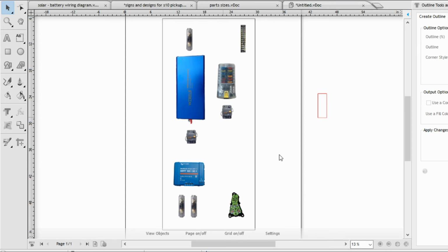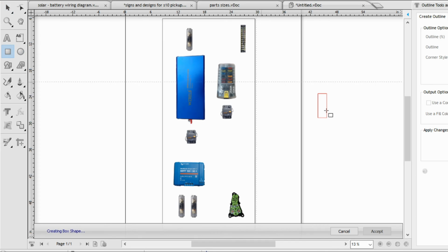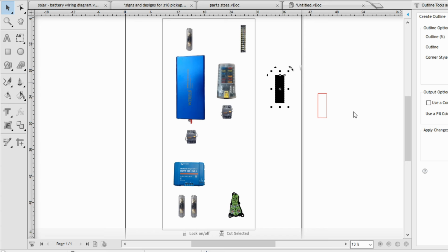And also, one other thing I'm going to be putting in here I don't have a picture of. I should have got that. It's an AC to DC charger. Put that right down here. And now I'll bring some battery wires up direct from the battery to this. And then this AC cord will come out and down. I'll take it somewhere. I'm not sure where yet. And that'll be plugged into the generator. So in case I've got 4 or 5 days of overcast, rainy days, I can keep the batteries topped up.